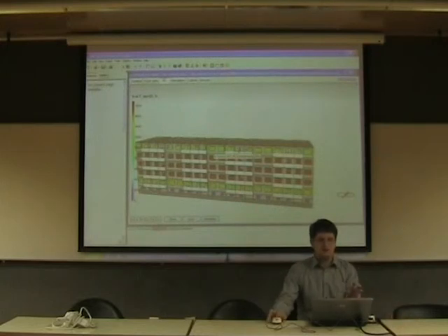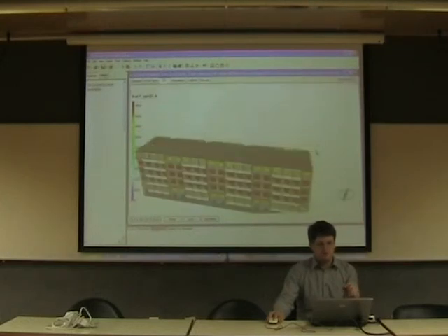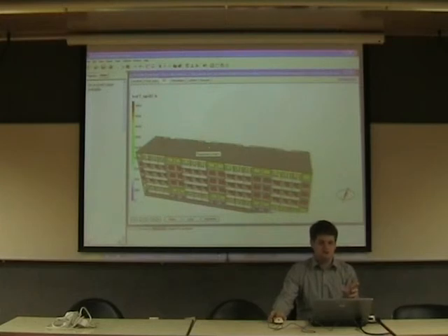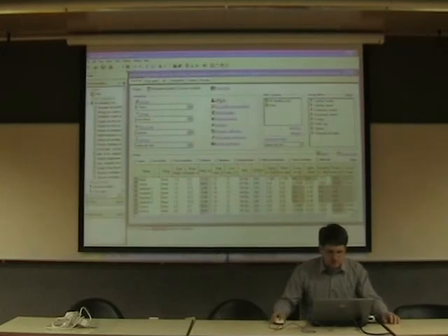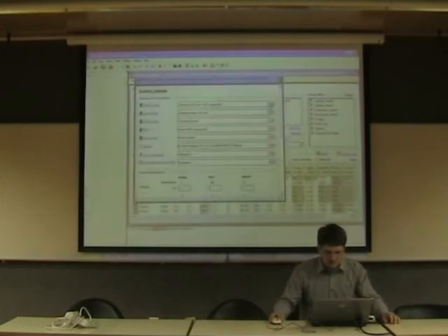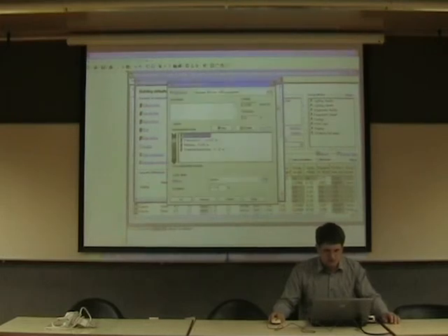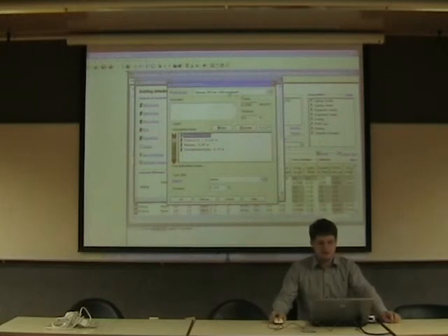For this house, I put 300 millimeters of extra thermal insulation outside, and also 300 millimeters of thermal insulation up to the floor and up to the roof. For the glasses, I can show you the U values from here. No, this is 150 millimeters of extra insulation.